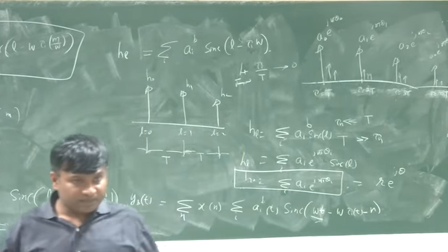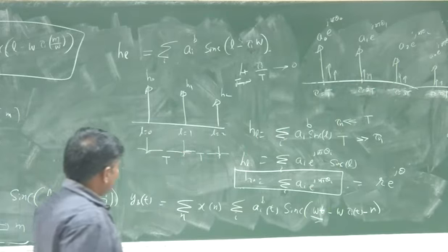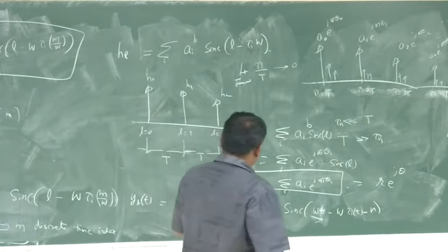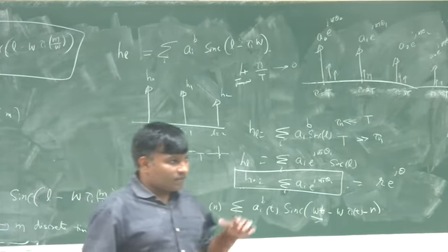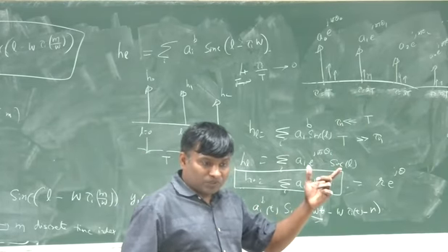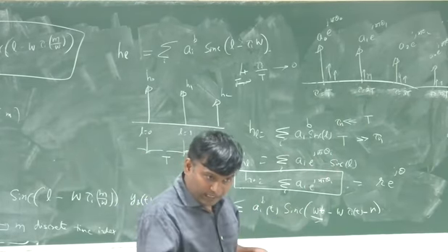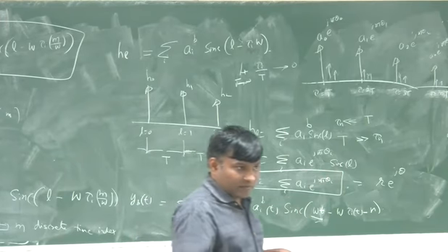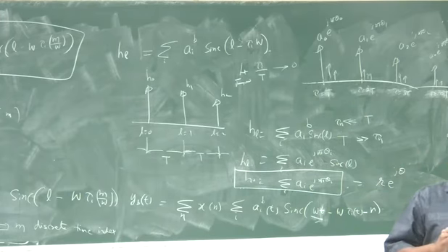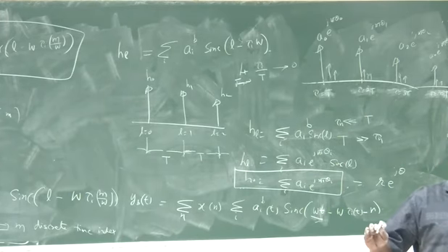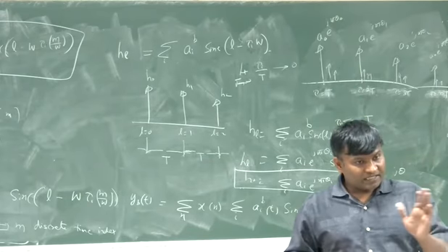Anyway, the point here is that ultimately, h of l's can be represented as taps with Rayleigh distribution and uniform phase, but they could be correlated. Sometimes we use the model where they are IID, assuming the average energy of each tap.